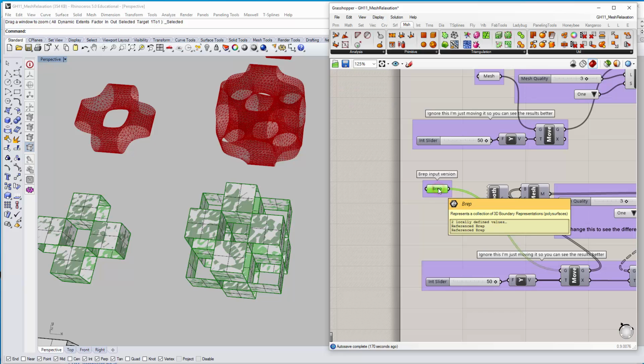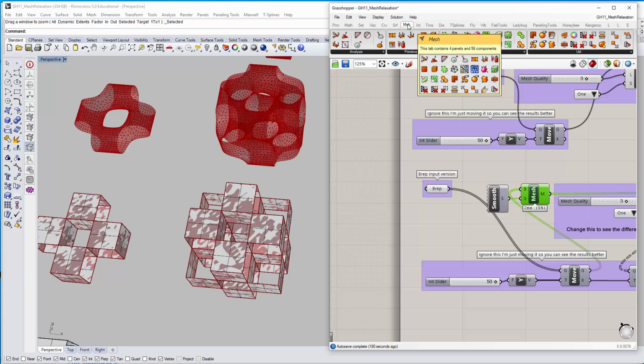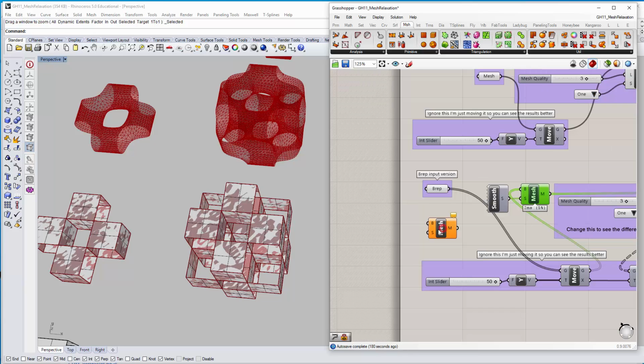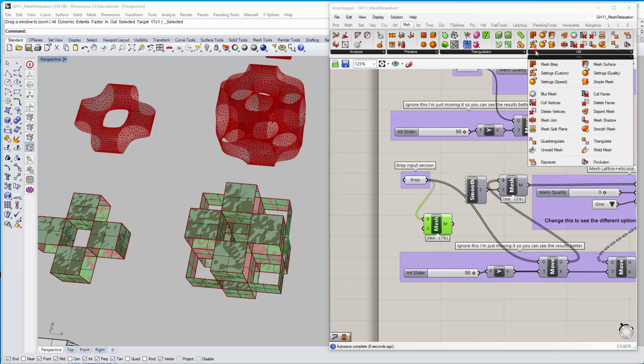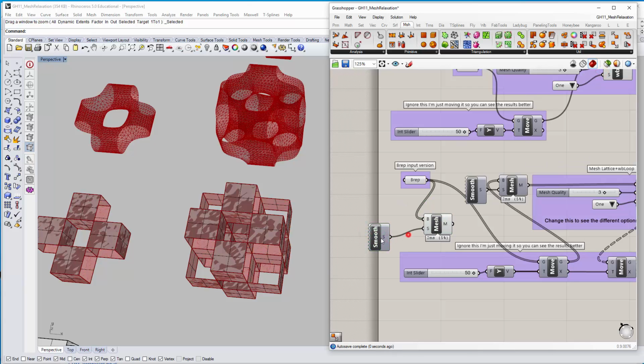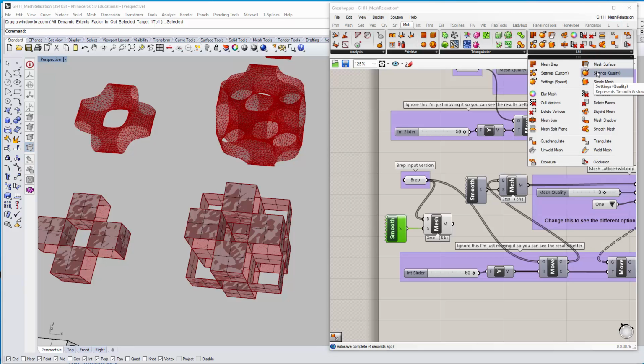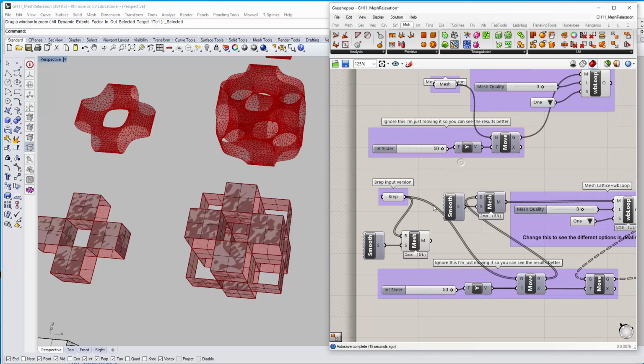But basically what I'm doing, I'm taking the B rep and I'm meshing it. So this is under, as you would guess, the mesh tab, mesh B rep. So you can take a B rep and mesh it, and if you mesh it, then it becomes a mesh, as you would imagine. And under here are settings, and so I'm going here, utility to set, and these are some of the setting options. I'm using the quality, which is the smooth setting. This is basically, in the 3D printing tutorial, we saw the left side of a slider and the right side of it, very simple and very detailed. So this is detailed, this is very simple, and it would give you a mesh that corresponds respectively.